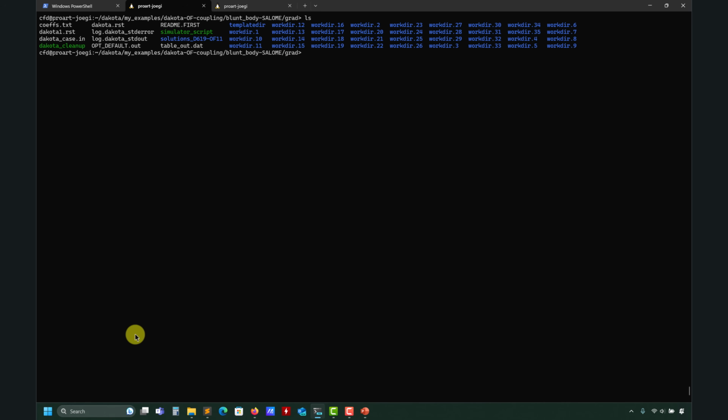So get familiar with restarting cases, because very often it might happen that your simulations are going to crash, and you need to restart from scratch. You can restart from that trace that you have, and this is very important. To be able to do this, most of the time, not necessarily because you have all the sensitivities here, but in some cases it might be necessary to have the trace of this folder. So that's why I also save the folders.